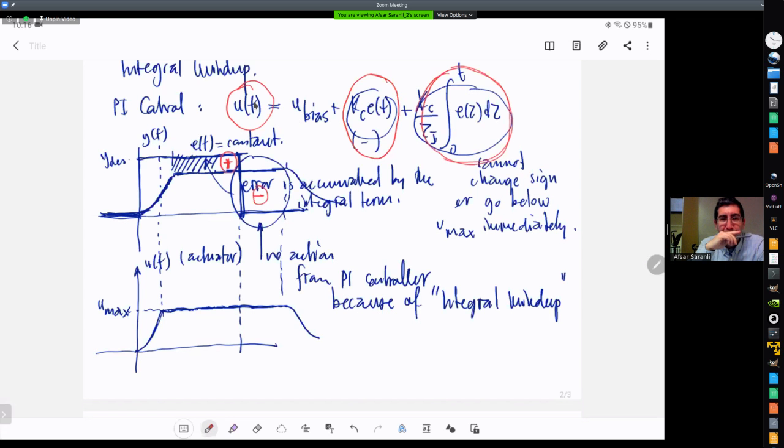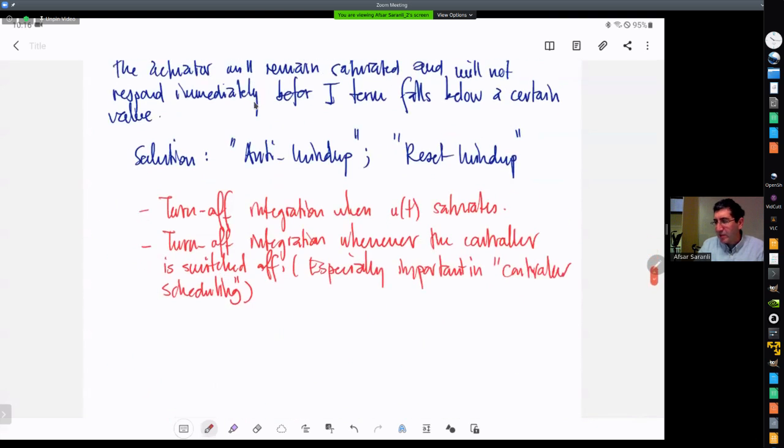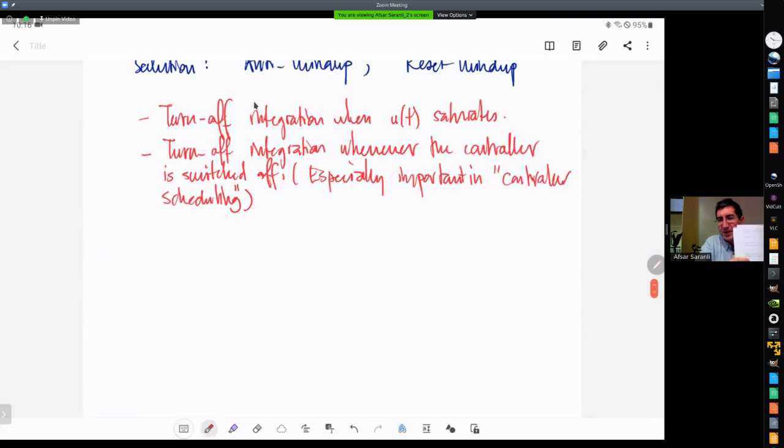Alright. So that is an important property of the integral controller, a practical property, because if you think about 302, we never talked about actuator saturation, any practical issues like that, okay? But in practice, any actuator, anything that your controller drives, actually has a physical limitation. So you can supply certain numbers to the actuator, but it really depends on what is achievable by the actuator.